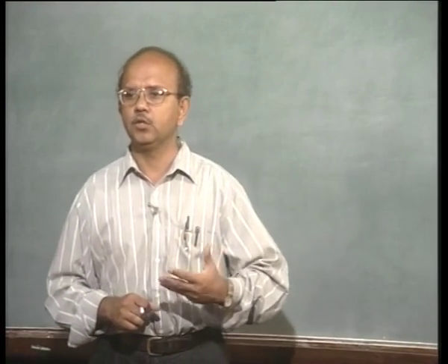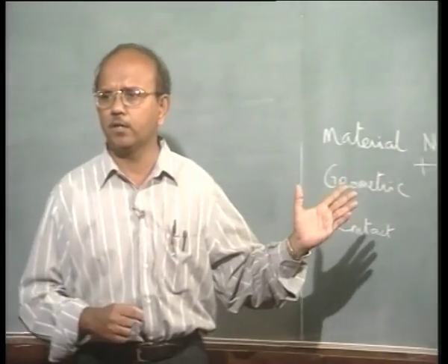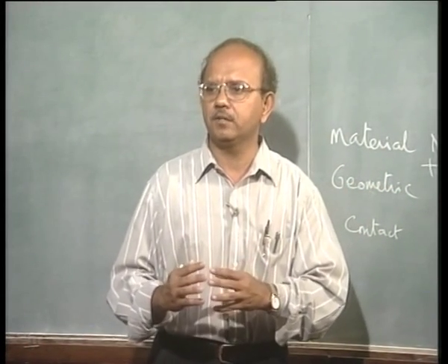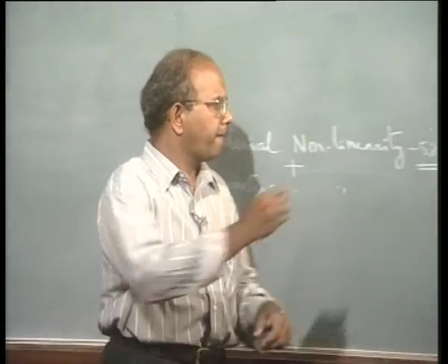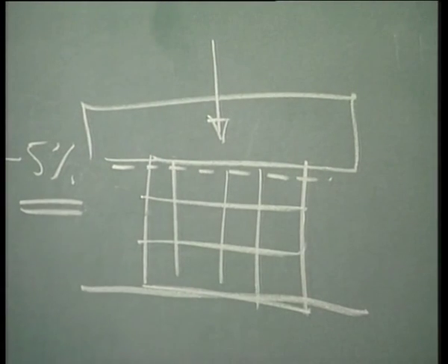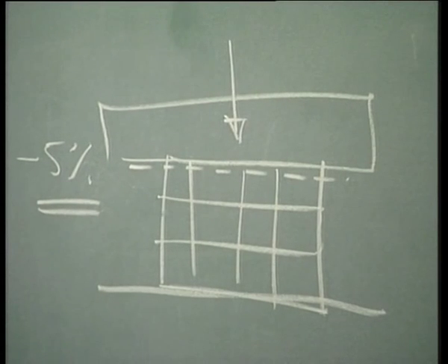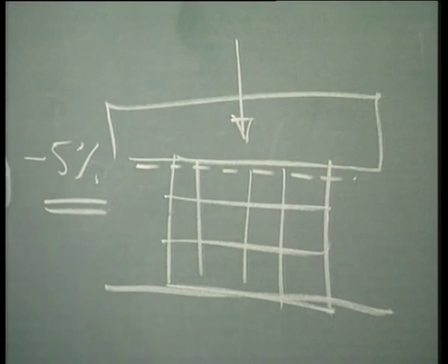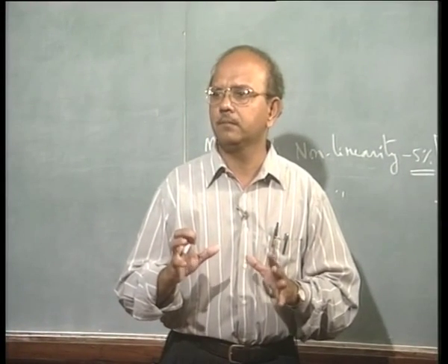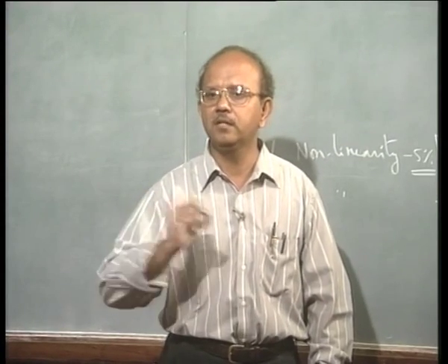Above 5%, you cannot use material nonlinearity alone. So, in other words, when do we use geometric nonlinearity? We use geometric nonlinearity when the deformation, suppose I am pushing it so it has come to just that level, very, very close. The original mesh and the deformed mesh are not very different, and whatever reference I take, they are the same. Then what do I say? I say that the problem is not geometrically nonlinear.